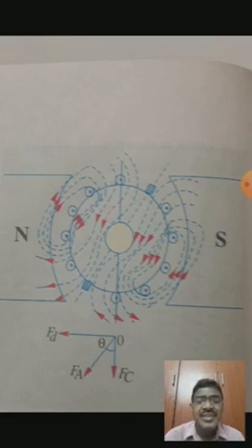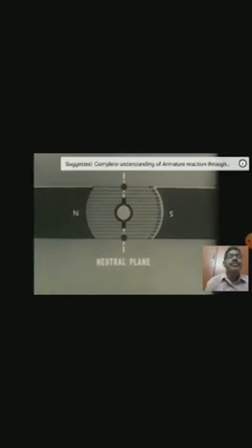Due to this unevenly distributed magnetic flux and the shifting of the magnetic neutral axis, sparking takes place between the commutator segments and the brushes. That is the cause of this cross magnetizing component. An animation video is shown for this armature reaction. Please observe. All these processes are associated with this video.